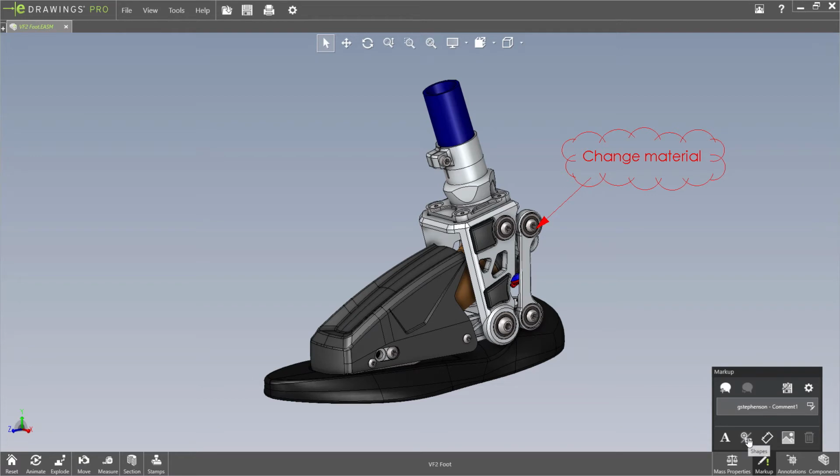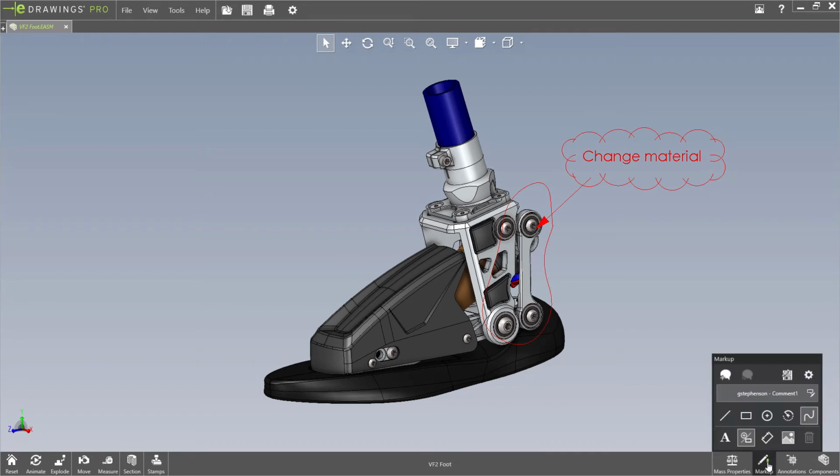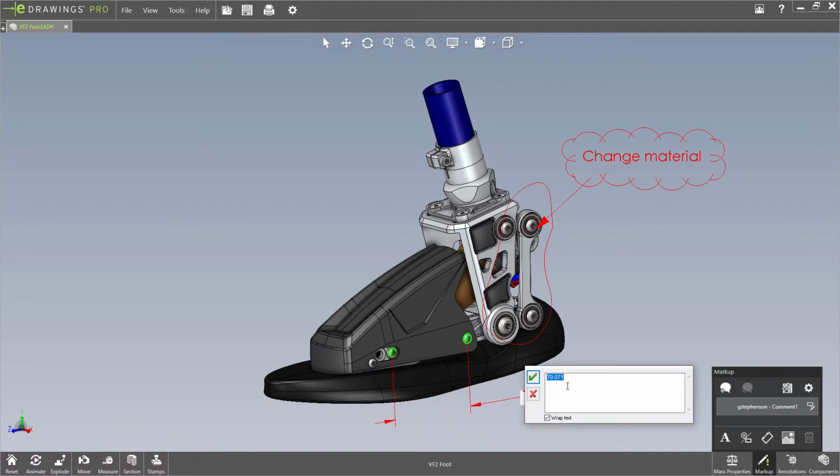And we have a range of other tools. If you wanted to scribble on this, we could start adding additional annotation styles to make that markup more visible. We can even add pictures and images in here as well. We could add dimensions on here. So if there was perhaps another change required, perhaps the distance between these bolts, we could add that on and say, increase to 75 millimeters. So again, a whole range of useful markup tools to allow feedback from the recipient.